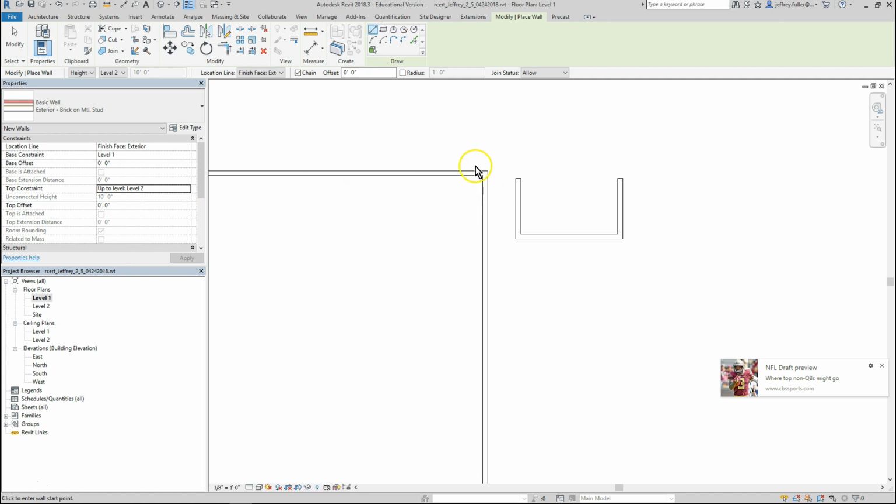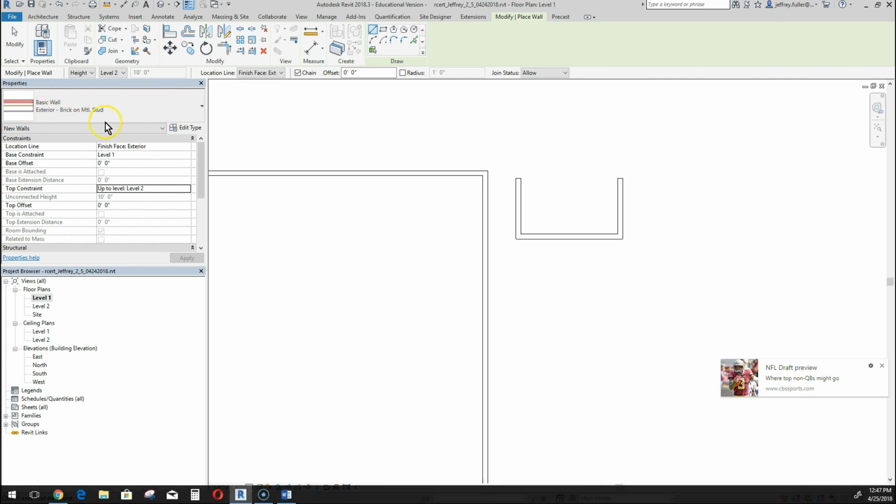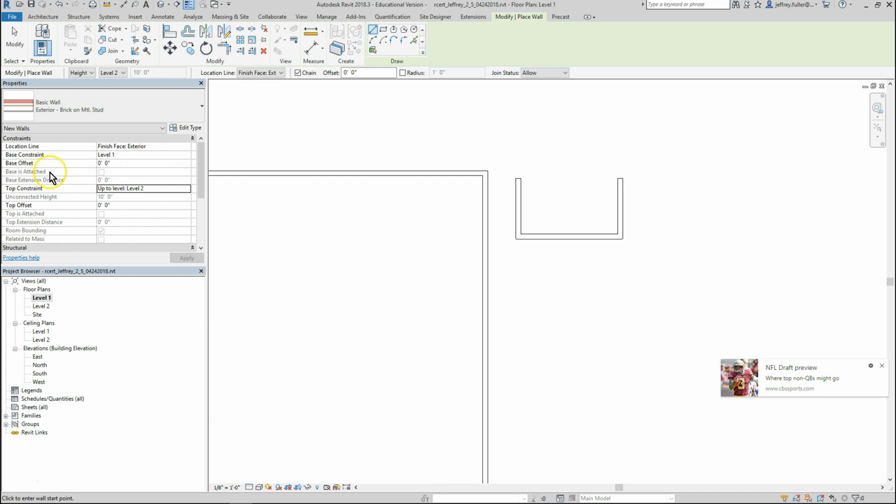I'm going to make sure that the same wall that I've been using is selected. Then I'm going to change the top constraint to up to Level 2. Notice that the cell under that, which is the unconnected height, has now grayed out, and its height in measurement, which used to read 20 feet, now says 10 feet, which is the height where my Level 2 begins. Right below the second smaller rectangle, draw another rectangle of similar proportions with the new settings. Now activate a three-dimensional view by clicking on the house icon in the Quick Access toolbar. You should be able to see the results of your adjustments.